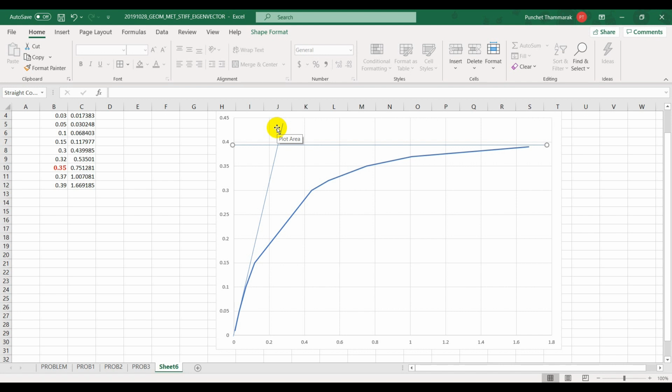The iterative solution affects only the nonlinear solution, because nonlinear solution depends on your presence of the axial force in the member. But if you do the linear solution without the consideration of the second order moment, well, no matter what P is, it doesn't affect the stiffness of your member, right? So you do not have to iterate.